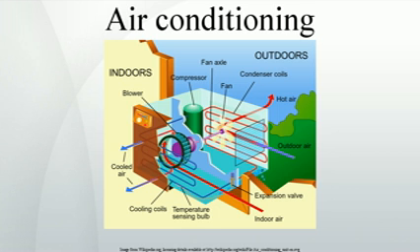R744 is an effective refrigerant with a global warming potential of 1. It must use higher compression to produce an equivalent cooling effect. Historically, Freon, a trade name for a family of haloalkane refrigerants manufactured by DuPont and other companies, was commonly used in air conditioners due to its superior stability and safety properties. However, these chlorine-bearing refrigerants reach the upper atmosphere when they escape.